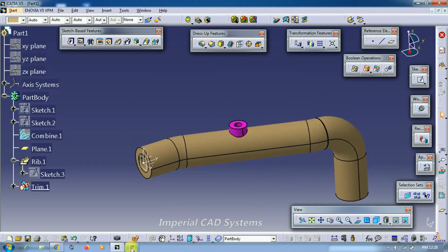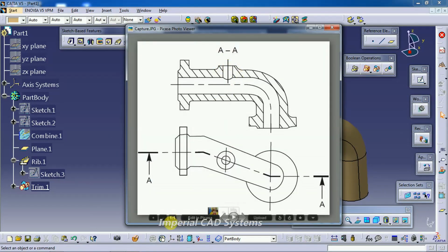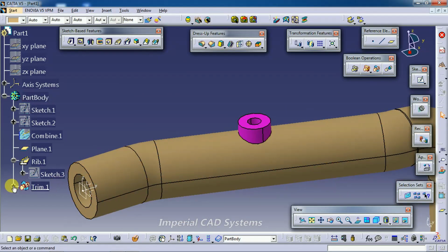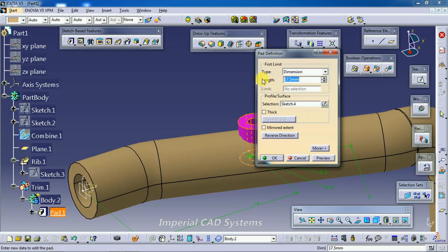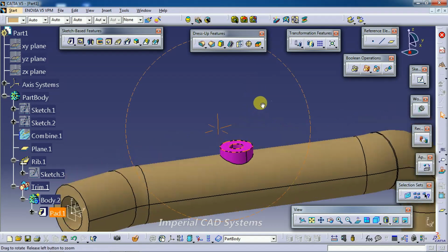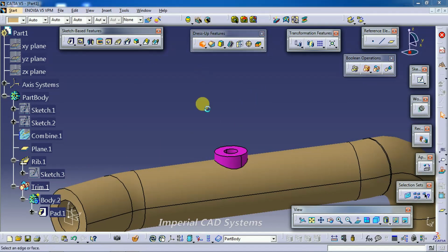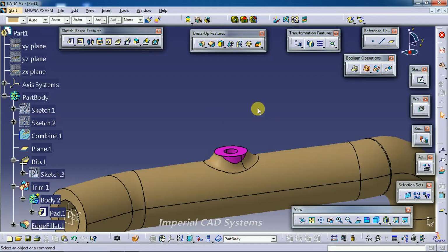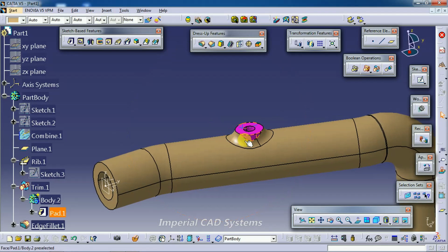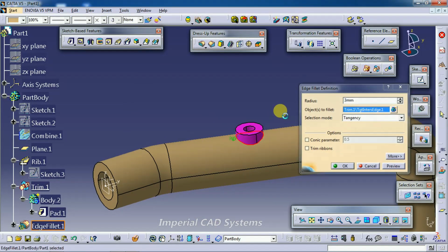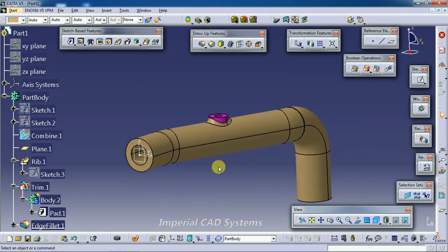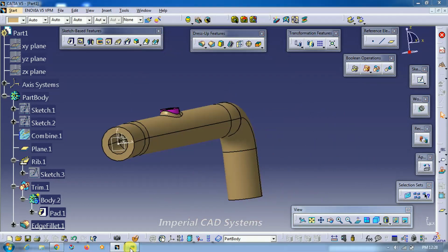Then fillet, to round the end. Slightly I reduce the height of this pad, double click, 17.5, instead of that I give 16 mm. Okay, fine. Now I apply fillet to the end, 5 mm. Let me see whether it accepts 5 mm. Yes, okay, fine. Now slightly I give some 3 mm. Yeah, it is filleted. Then what else remains?